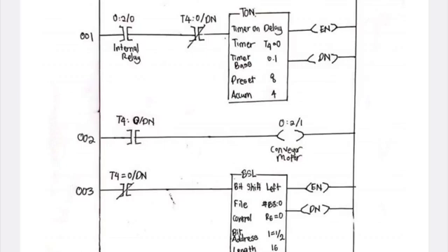In the PLC program, based on the PLC ladder diagram, rung 001 and rung 002 are used to operate the conveyor motor. Assuming it takes 0.5 seconds to cap a bottle, capping is performed when the conveyor is stopped for a second. When push button input 1/0 is closed, it will energize the internal relay. Then conveyor motor output 2/1 runs for a moment and stops for a second. Then the timer is in auto reset mode by T4:0/DN in series with it.